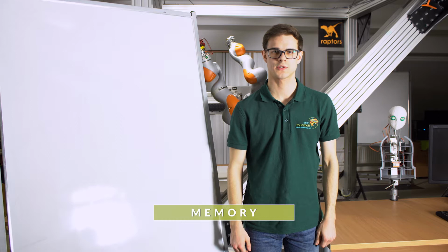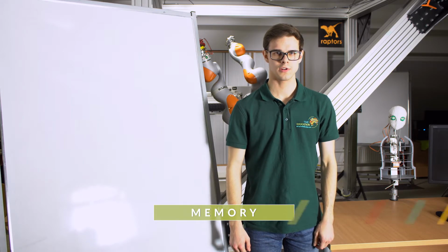Memory is a system which stores data. Usually, information can be saved, read, or overwritten unless you deal with a type of memory that can only be written once. Memory is divided into 2 groups: volatile and non-volatile. Volatile memory, also called RAM or cache, erases all stored data when the power source is turned off. Non-volatile memory, known as ROM or flash, stores data permanently.